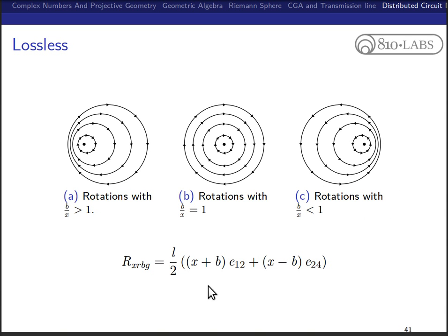So you can really use this to study mismatched transmission lines in a very concrete way, and we can generate these things. These things are kind of hard to describe mathematically. You have to cascade a matrix of an impedance step and a matched transmission line and things like that. But here we can express it all as just one rotation.